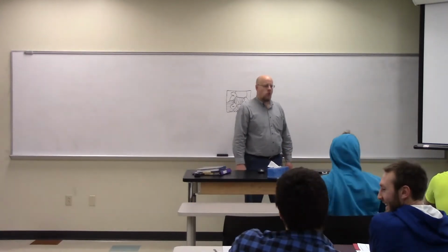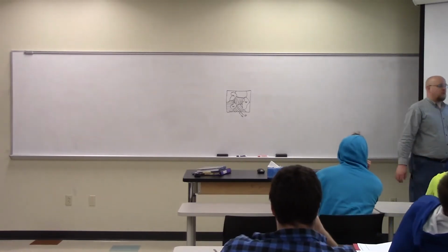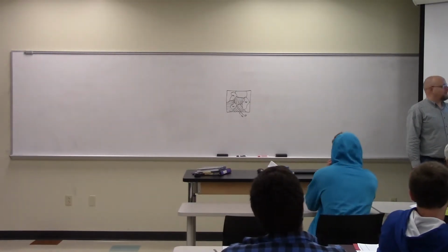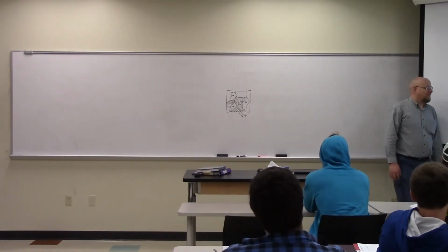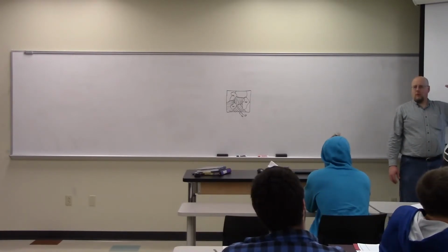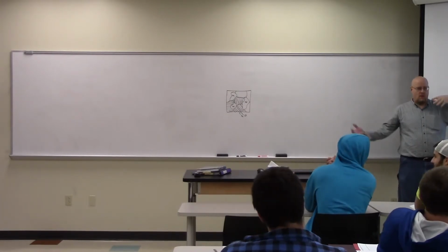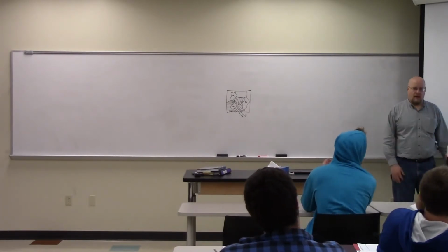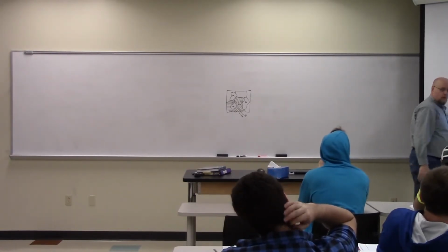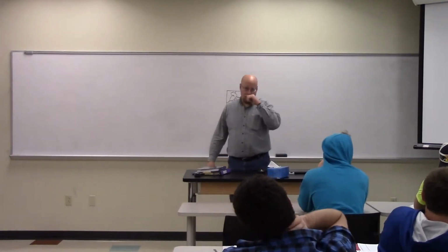And how do you know if it's right there in the middle, how do you know if it's coarse perlite? So it's my job to make sure that I don't put you right in the middle. If it's right in the middle, something's probably been done wrong. I will tell you, if I tell you to quench to a certain temperature, then hold it for a certain amount of time, then quench to a certain temperature, all that kind of stuff, like I gave you descriptions in class, draw all your lines vertically. You quench, you hold, you quench, you hold. Just assume that everything's vertical and horizontal.